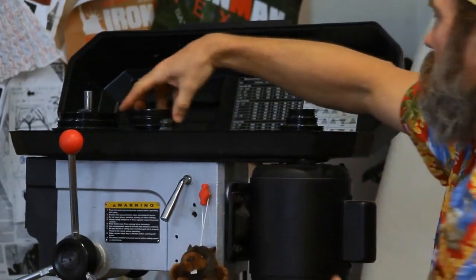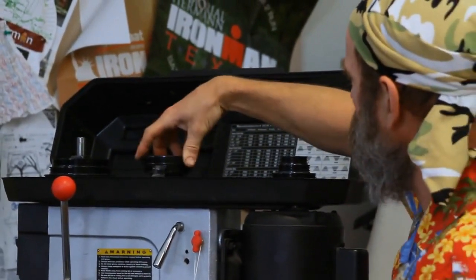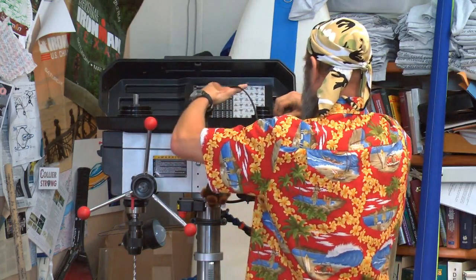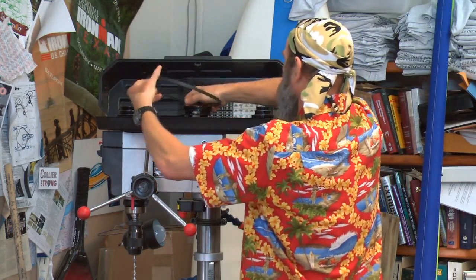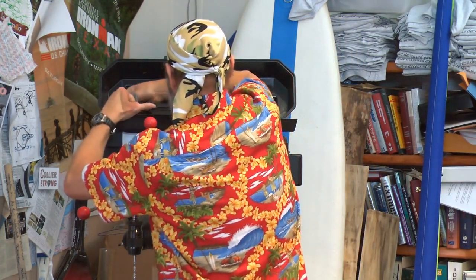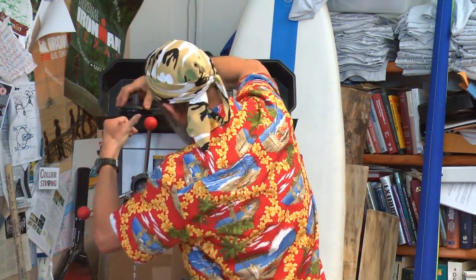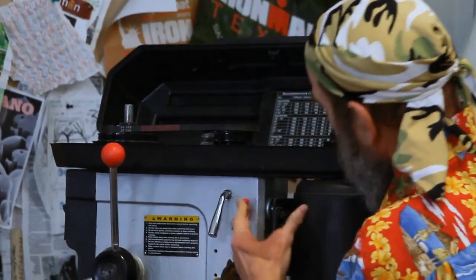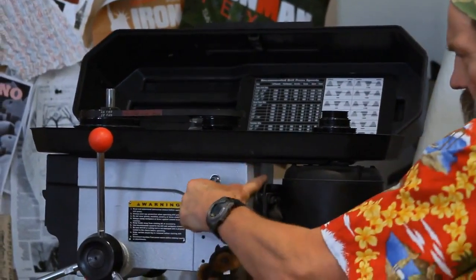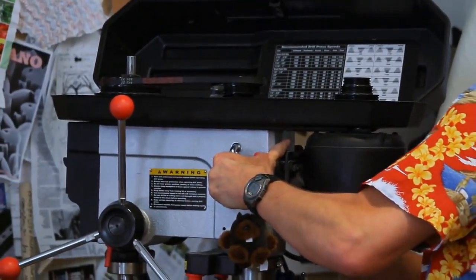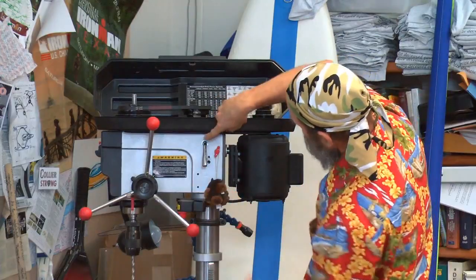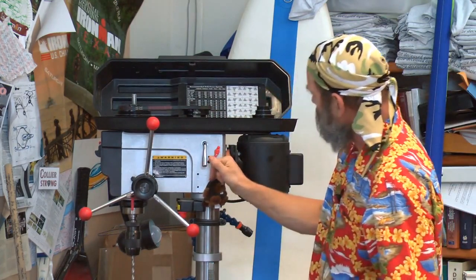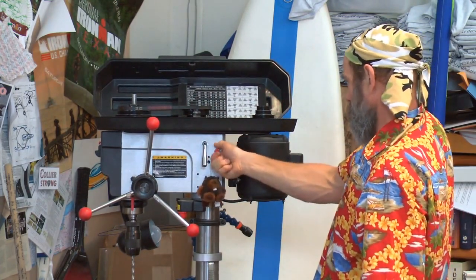And notice the way this pulley here swivels. This design was actually done pretty well. It allows that intermediary pulley to come to an equilibrium position. And watch how I can change the speed. And then, now see, I got to pull it tight. See, this is the lever that lets me put tension on it. So that was done well. There's a little rack in there. We'll learn about the next topic on rack and pinion. There's teeth on the inside of here that drive teeth on these little round shafts in here that extend through. And this is my lock.